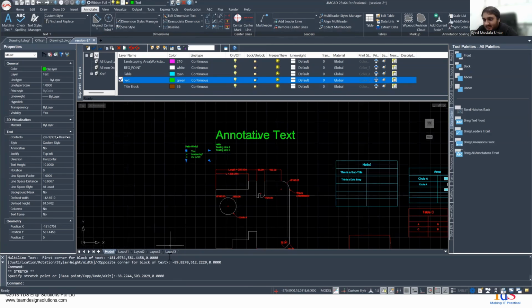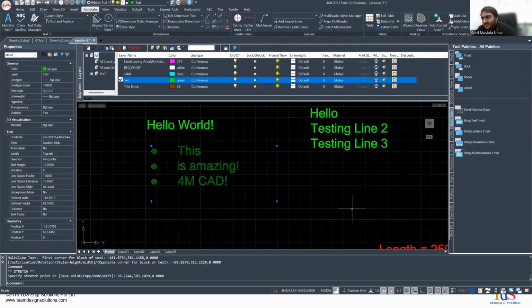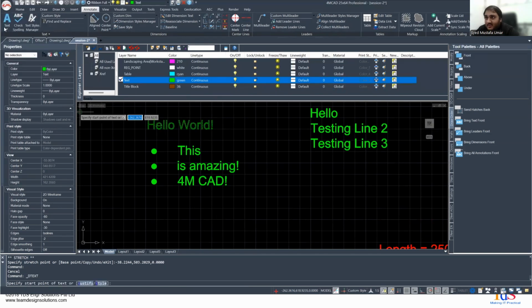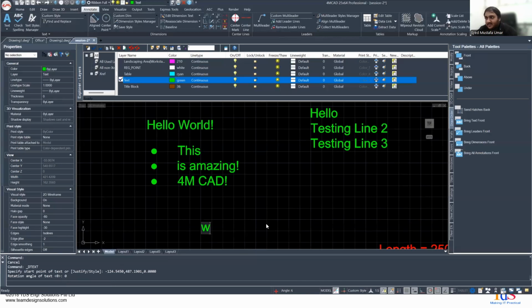So keep that in mind when you are coming up with your drawings, and especially when you are in this layout space where you are in the paper view and coming up with what the final picture for your drawing is going to look like. All of these small, minor things are quite important. These should be kept in mind. But remember that the text style manager is what allows you to manage this text. And once you are creating a piece of text or a multi-line text, this is where you can actually go ahead and edit it.